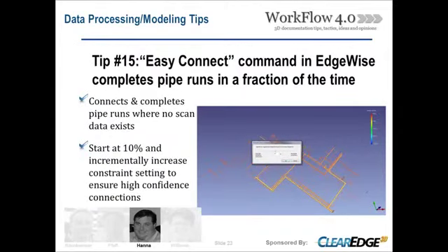Yeah, that's a great point Larry brings up, and I think it's essential as well that when you're doing modeling, you preserve the scanner coordinates so that when you're adding more data, everything's coming in at the correct place in the Revit model.